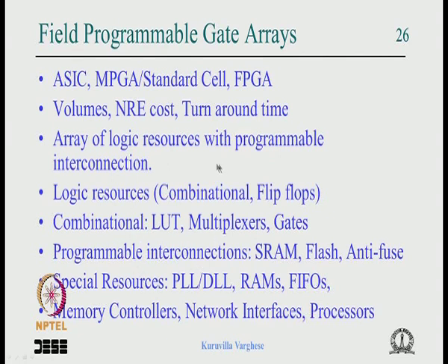And if you look at the programmable interconnection, these are the technologies used: SRAMs, that is static RAM, which is a bit of an unfortunate name, though at a top level the name is correct, but it might mislead you in terms of the technology used for interconnection. The flash transistor and something called anti-fuse, okay, or as the Americans say, anti-fuse. So here the anti-fuse is a kind of opposite of a fuse.